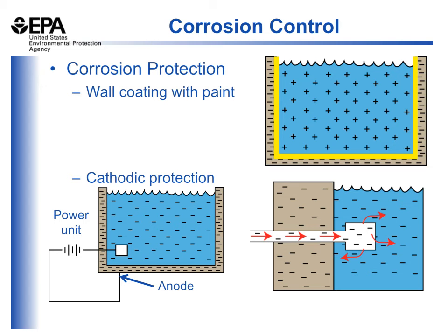These cathodic protection systems are an economical alternative to periodic repainting and associated downtime for repair, and they're fairly inexpensive. However, the area of the tank above the water line is not protected in that case and can still corrode. And the bottom of your tank may be covered with silt or debris or sand at varying depths, at which point the tank is no longer protected there either. So, the ideal type of corrosion protection is the combination of both concepts, painting and cathodic protection.